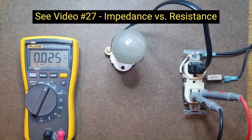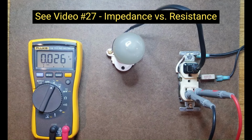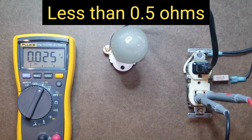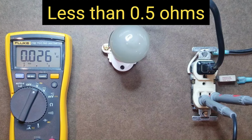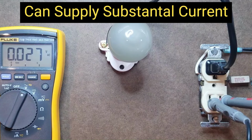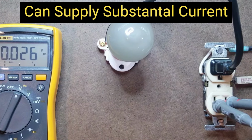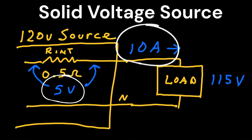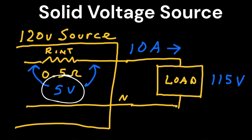The internal or output resistance of a voltage source like a 120 volt AC outlet is very, very low, typically less than 0.5 ohms. This low output resistance allows it to supply a substantial amount of current without a significant voltage drop. For example, if you were to try and draw 10 amps from the source, it would only result in a 5 volt drop across that 0.5 ohms of impedance.